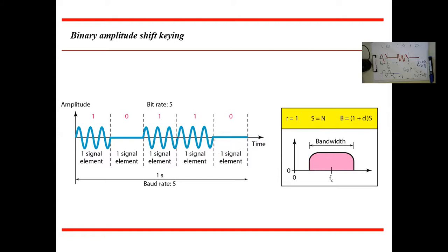It's either 0 or a carrier. So whenever you have added noise over the signal, you can easily detect it in the receiver. This is a true example to understand why digital modulation noise immunity is much better than analog modulation noise immunity. In both cases, we are comparing apple to apple. We are comparing amplitude modulation to amplitude shift keying, but as you can see, in amplitude shift keying the noise immunity is much better than in amplitude modulation.